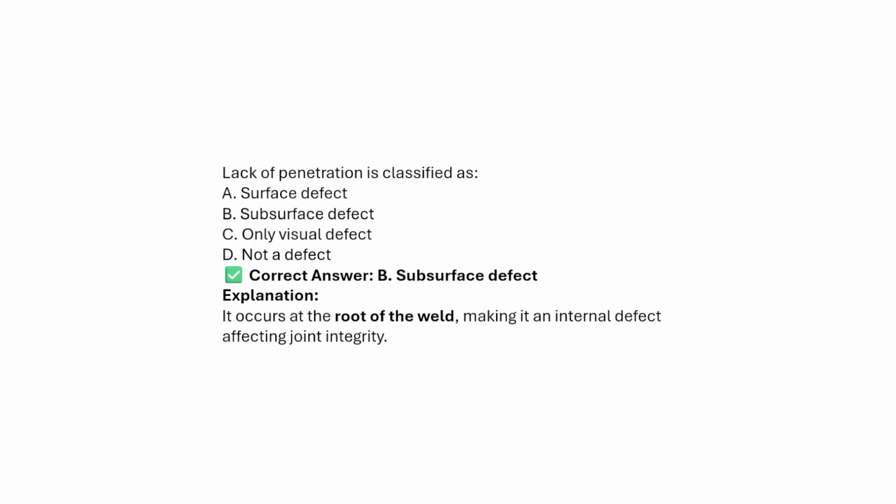Lack of penetration is classified as a surface defect, subsurface defect, only visible defect, or not a defect? The answer will be the subsurface defect. It occurs at the root of the weld, making it an internal defect affecting the joint integrity.